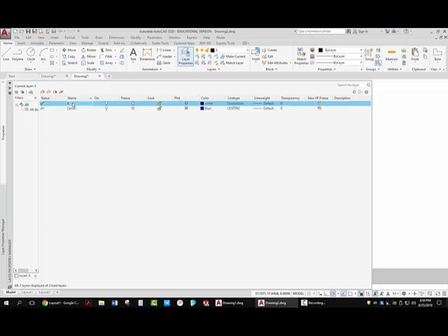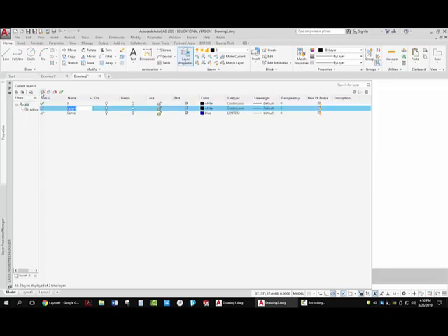I'm going to go back and select layer 0. By the way, you cannot change the name of layer 0, you can't delete layer 0, and you should never draw on layer 0 unless you are specifically creating a block definition. I go back to the little layer start.